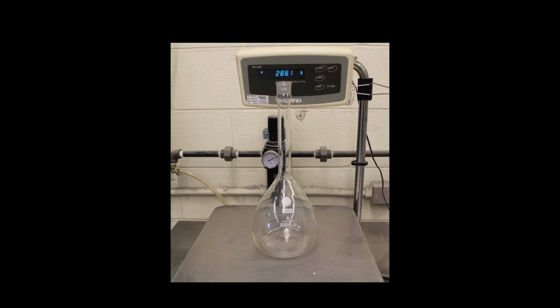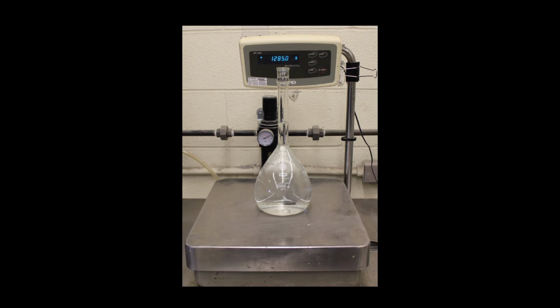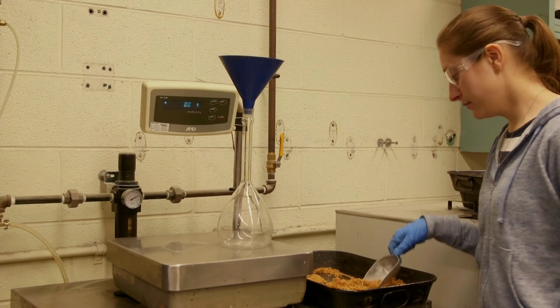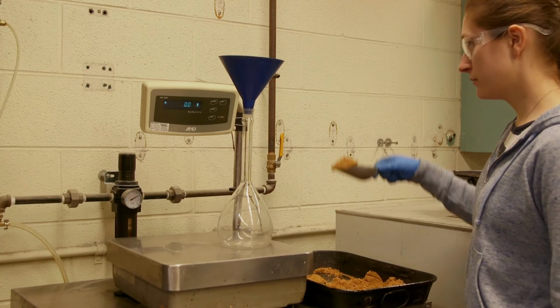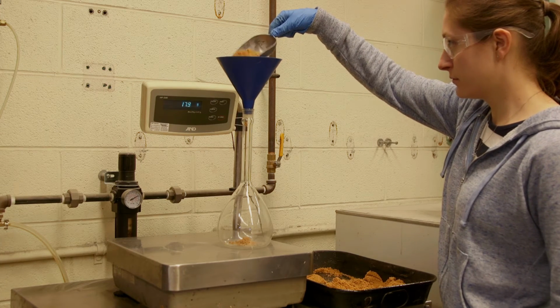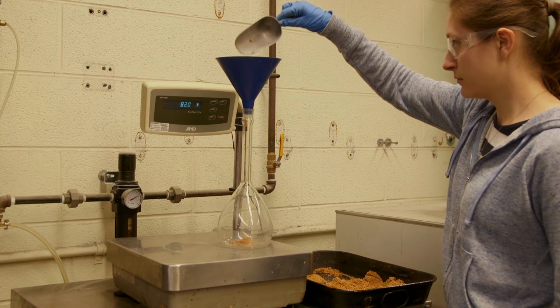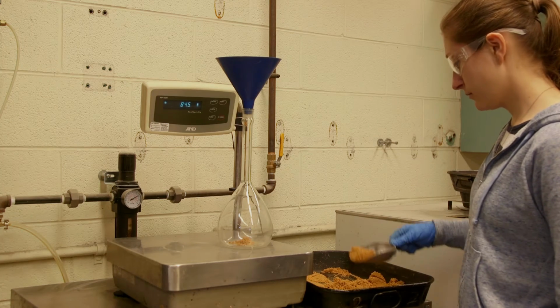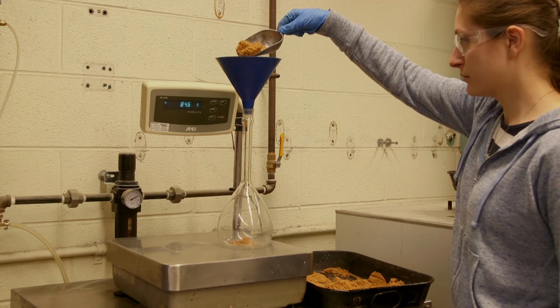Determine the mass of the dry pycnometer flask. Calibrate the pycnometer flask by filling it with water to the calibration line. Place the flask on the scale to determine the mass of the flask plus water. Pour the water out of the pycnometer flask and place 500 plus or minus 10 grams of the SSD aggregate into the pycnometer and fill with water to 90% of the pycnometer capacity.